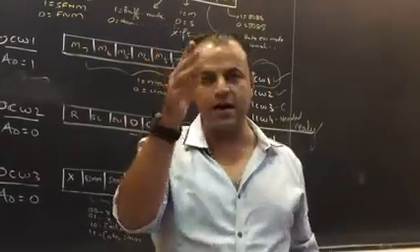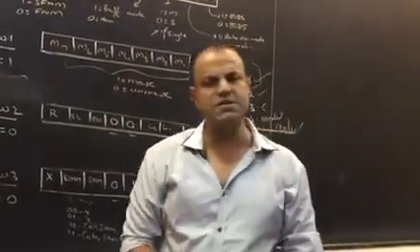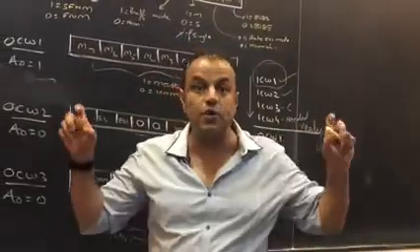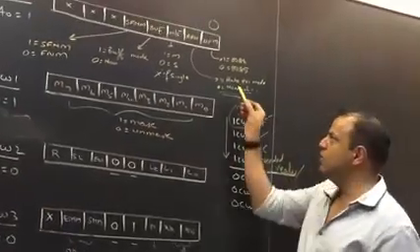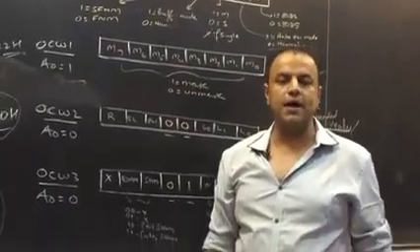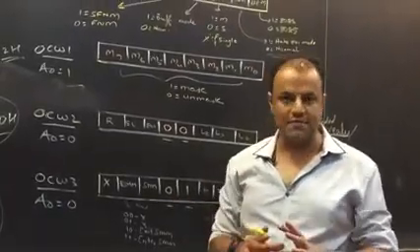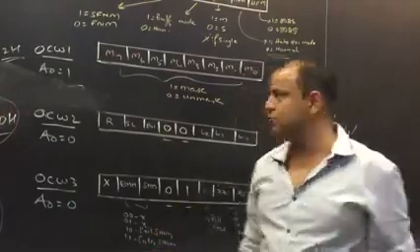automatically. On the third INTA bar, the bit will automatically become 0. So which is a better way of working, normal EOI. Hence it is called normal EOI. So that is also the default. 0 is normal EOI mode, 1 is auto EOI mode. I would love to explain those modes again, but I'll be just repeating the same information again and again. I have made a full video on it. Please check out that video to understand EOI modes.